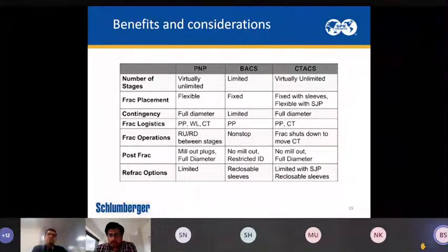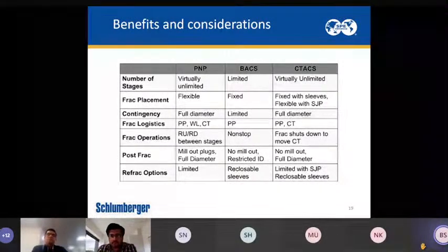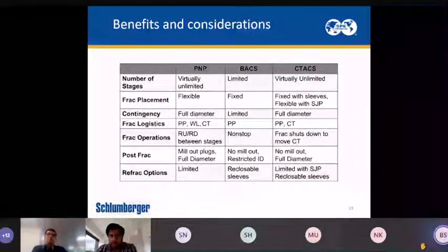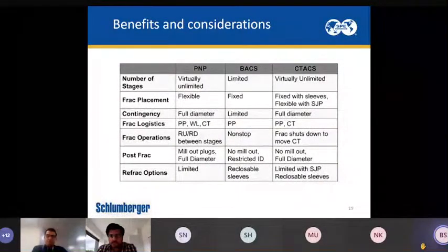They worked well in oil wells, where they degraded during flowback, but in pure gas producing wells we have seen that diverters sometimes do not flow back or degrade, and compromise production. You mentioned the degradation in your presentation, but can you elaborate on the mechanism by which this synthetic material is going to degrade itself after pumping?